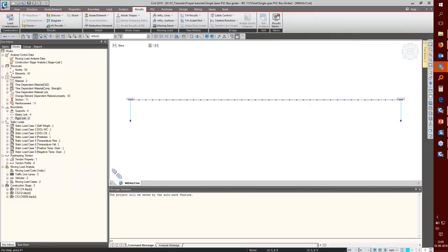Then we have, how to model friction of a metallic bearing in the direction of its movement. Friction which has a relationship with axial load in the bearing. Okay. This is a very interesting question, because everyone who has gone through the code has seen this clause where we need to model the friction bearing for our bearings, right? So we need to model some stiffness.